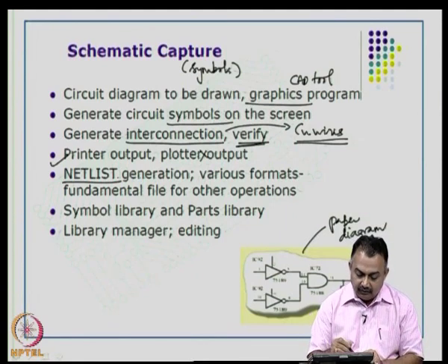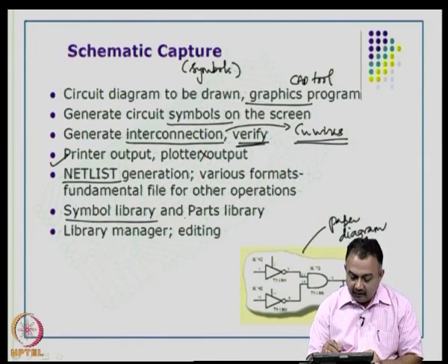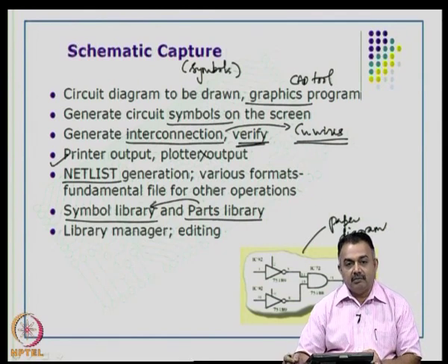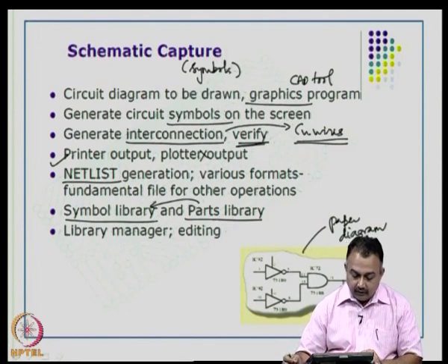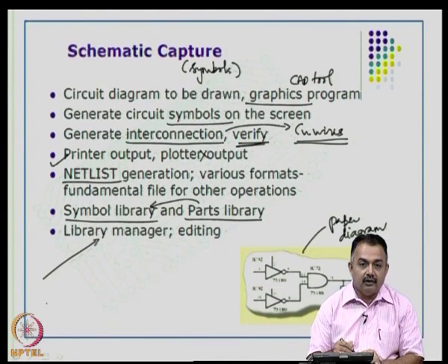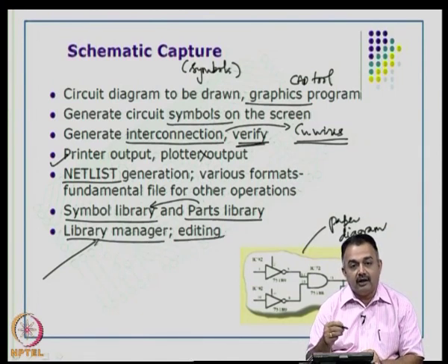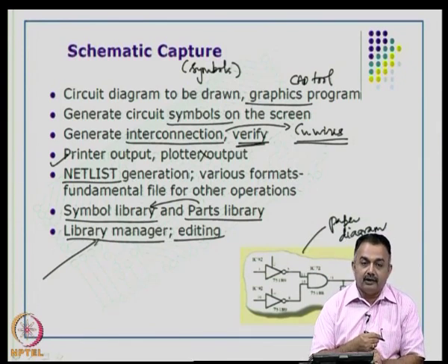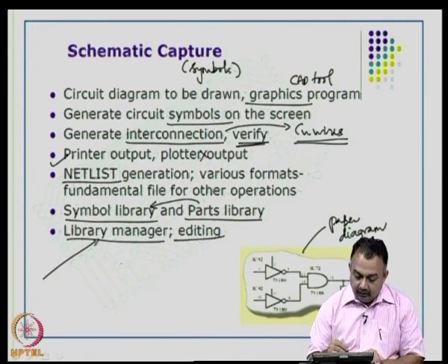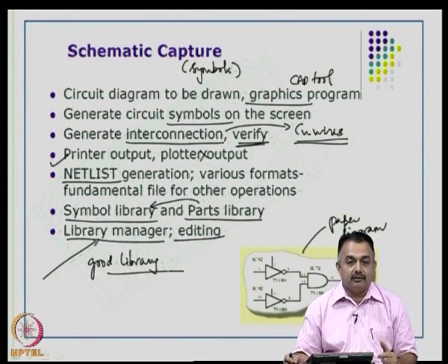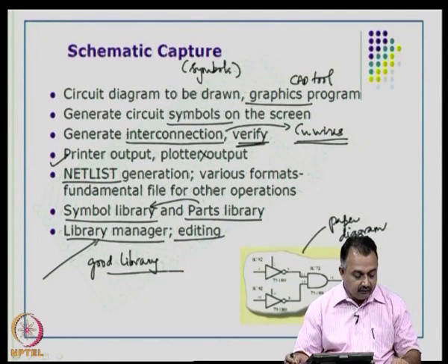To do a schematic capture, the first requirement is to make sure you have a very good symbol library, and afterwards a parts library that you need to annotate or relate to the symbols that you have picked for that particular design. So, if you are in an organization or an institution where a lot of designs are being done, you have to look carefully at a CADware that provides a very good library manager, which can be edited and utilized for your future component symbols that may not be available online. Okay. So, make sure that when you buy a software, you have a very good library. This is a must, because you are paying a large amount of money for this source of information where you can pick these symbols and start working with your design.